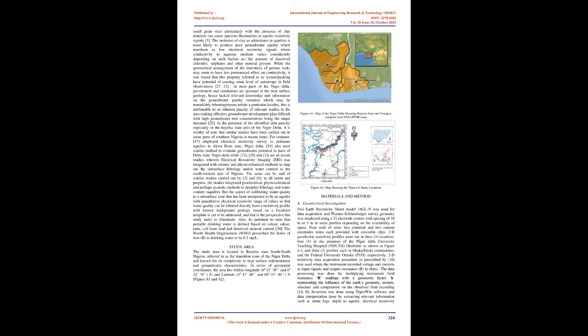[22]. In groundwater exploration, various geophysical methods have been employed to locate suitable points for productive boreholes. One of such methods commonly used is the electrical resistivity method, in which vertical electrical sounding, VES, and horizontal profiling, HP, are commonly carried out [24, 6, 14, 12, and 15].